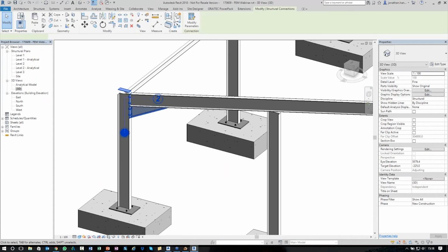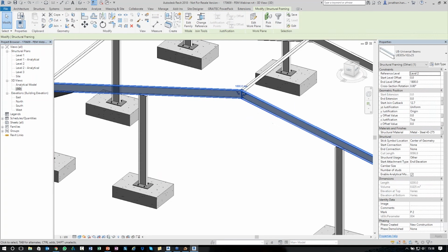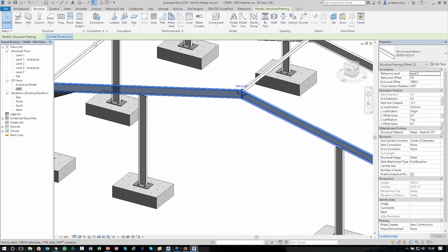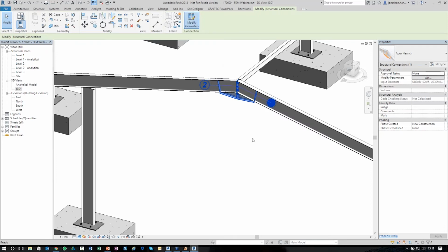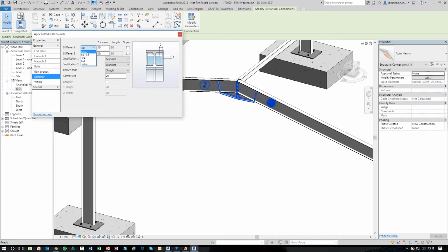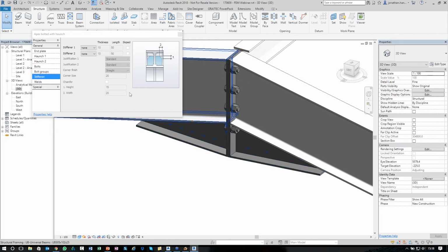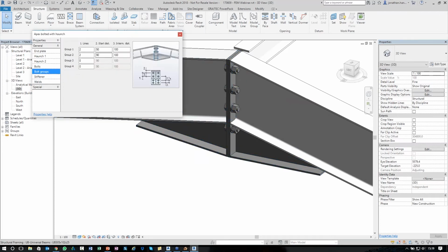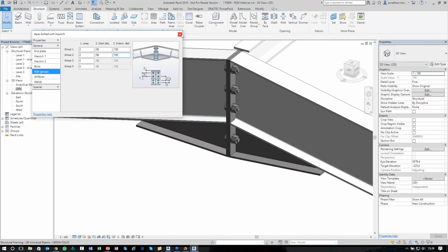And we look at this where we've got a gable post. So again, beam to beam, go to structure, connection, and we look at what we need, and I've got this gable wall end plate. You will notice that something strange happens, and this is because of the bearing member, what is the supporting member, and what is the prioritized member. In this case you can see that it's cut it off in line with the gable, so I simply stretch that up to there, and you can see the way it goes green.